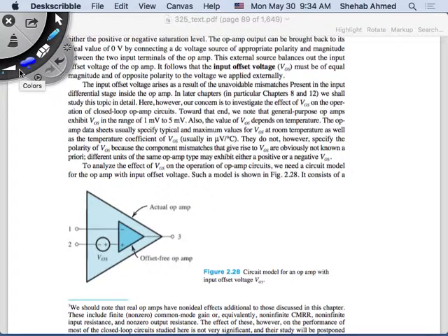We're also going to look at the effect of having current actually flowing into the terminals of the op-amp. These are called bias currents. Bias currents are currents that are not due to your input impedance. They are actually due to the fact that you have circuits inside here that require certain operating points, meaning there will be certain currents flowing and voltages across the transistors that make up this circuit that are going to force small values of current to go through the op-amp. This has nothing to do with your input impedance, or with the circuit that you created around it. They're there because of the device. And we will see what the effect of those are.